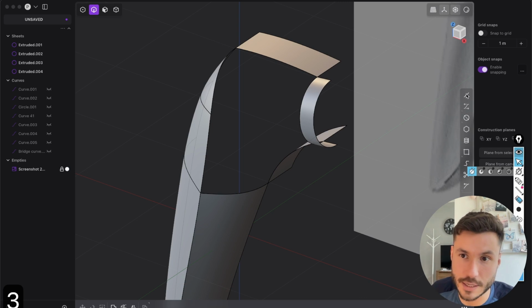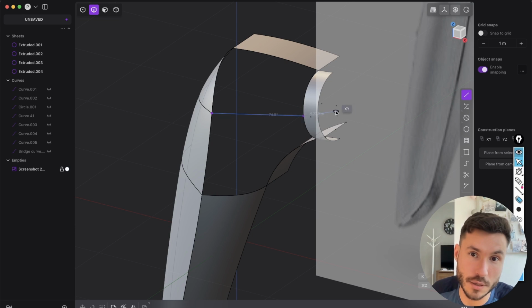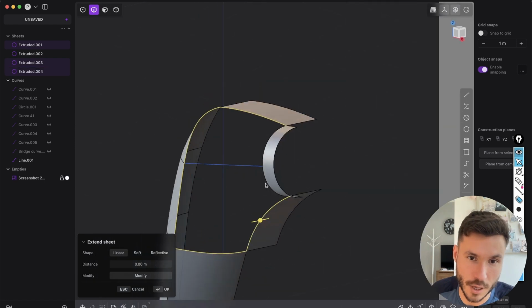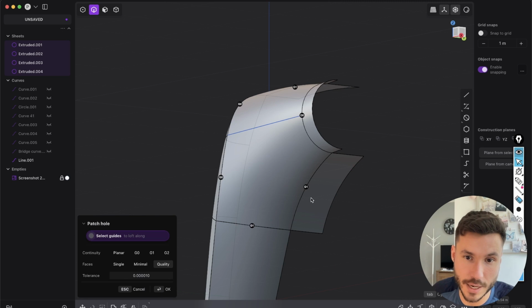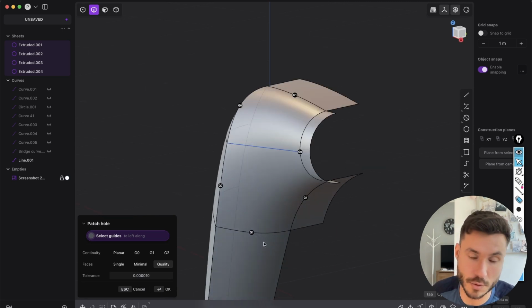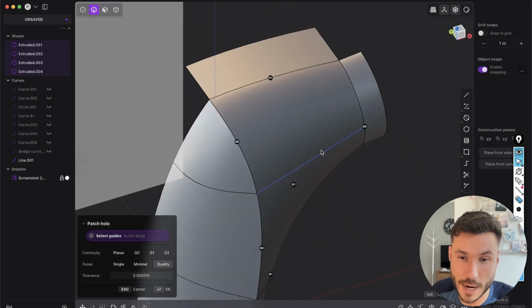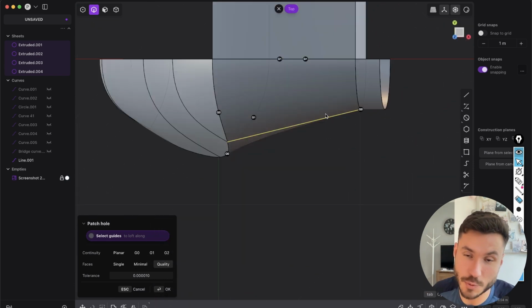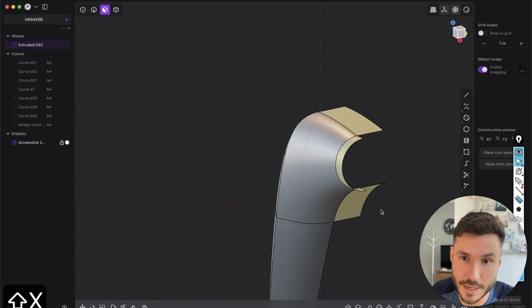And you can just create here a line or press Shift A and just go to this edge because we have already a break, and just go here to the middle, right click, and do again, select the boundary edges for our beautiful patch and patch, and then G1 again, G1 and G1, everything where it has to be smooth. So G1 is tangency, so smooth surface. And you see from top, it looks wonky. But if we now, while we are in the patch, press Shift click this curve, bam, you see we get much more control into our patch. So very useful.